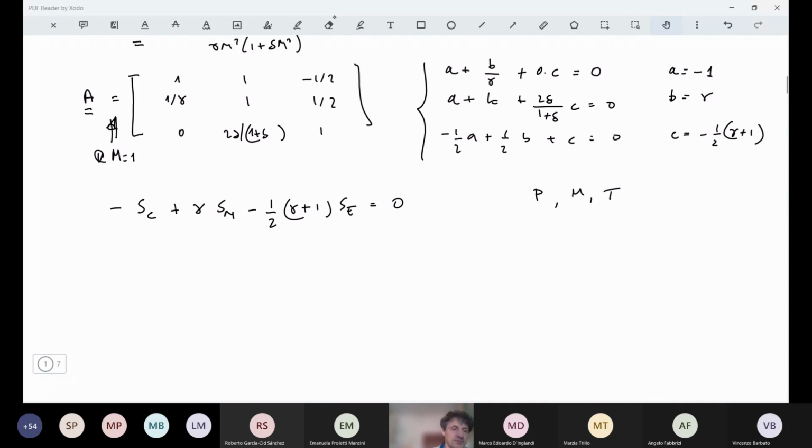from the thermodynamics laws, we have dH equal to TdS plus dP over rho, where S and H are specific values with respect to mass in this expression. We can also rearrange this, dividing everything by T and recalling that dH is Cp dT for a thermally perfect gas. So we can also identify a relation for the entropy as a function of temperature and pressure, which we have already expressed as a function of the Mach number. I'm intending the differential part of all these quantities.